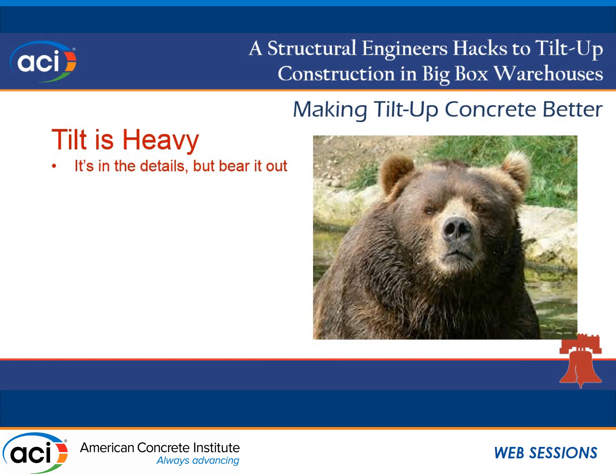When designing those panels, always bear, okay? Bear concrete on concrete if you can. Set back a panel edge so that your flying panels that come over the top sit on other tilt-up panels. It's more stable during erection, it's easier to brace, and you spend less time with a crane up in the air and a guy out there with a welder trying to fix things together.